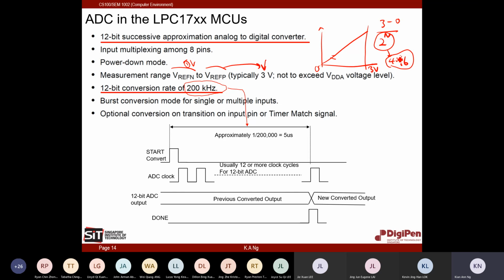If your ADC resolution is not what it is promised, you may get oscillation. Then your servo motor may run out of control. Just take note of that. At least for this course, you may not see it, but in your future adventures as an engineer, you may actually see it.